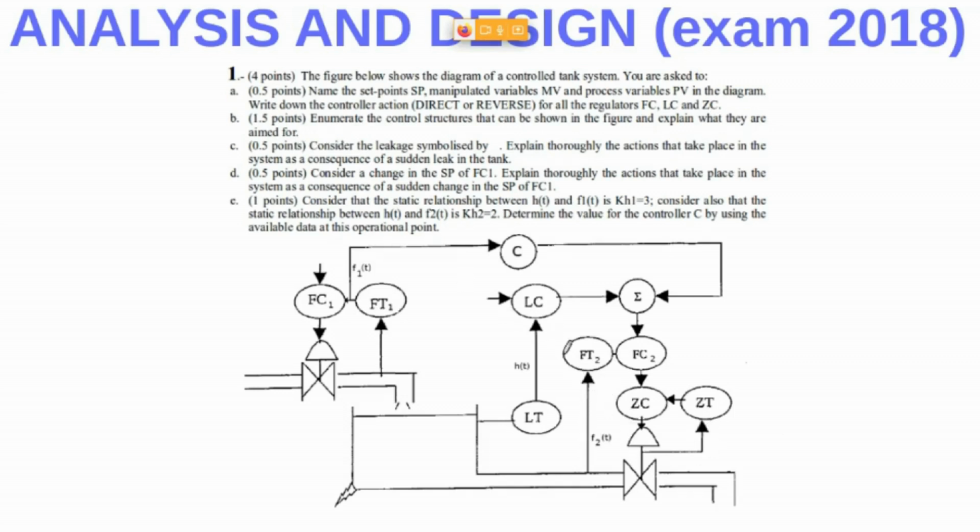As you can see here, we have a main level control. This is the primary loop. The output of this controller becomes the input of an inner flow loop. And the output of this inner flow loop is the input of an inner position loop, the position of this valve, right? If it's open at a specific point, that's the position of the valve. That means the opening rate.